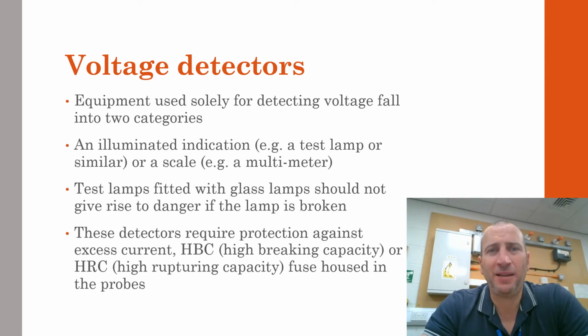If using a test lamp that is fitted with a glass lamp, it should not expose the user to danger if the lamp is broken. Consider the implications of a smashed light bulb and a light fitting. With the power still connected, simply touching the exposed terminals can cause a serious electric shock.